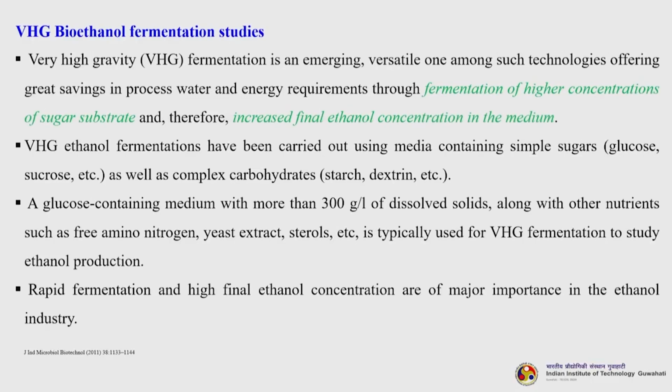So, let us understand VHG bioethanol fermentation. VHG fermentation is an emerging versatile technology among such technologies, offering great savings in process water and energy requirements through fermentation of higher concentrations of sugar substrate and therefore increased final ethanol concentration in the medium.